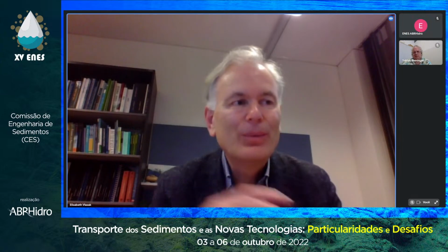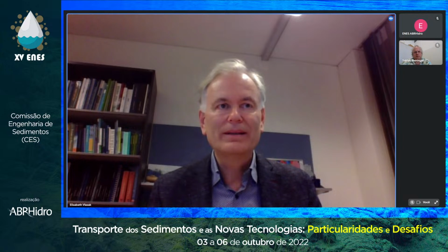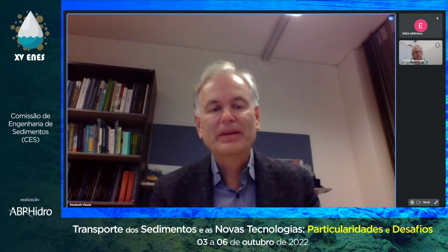But it's not the whole truth, because some fish can sustain higher concentrations, and it's also the timing. We are right now doing a research project to show that it's not always this 1 gram; it can be much higher if it is only short. I told you about this stress index: the concentration and the time we have to observe, but also, if possible, the distribution of the sediment cloud, because fish might find in the cross section some area where there's lower concentration.